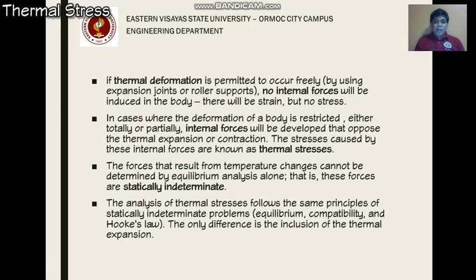So if we are solving thermal stresses, we will also apply the principle of statically indeterminate problems. The analysis of thermal stresses follows the same principles of statically indeterminate problems. So first, determining the equilibrium equations, followed by determining the compatibility equation and applying Hooke's law. So the only difference is the inclusion of the thermal expansion.